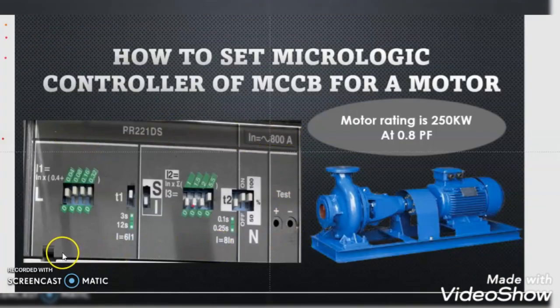I hope you got the importance of this Micrologic controller, as an incorrect setting will lead to continuous tripping of the motor, and if the setting of this Micrologic controller is wrong, there is also a chance that your motor will burn out. I will give you one example here.